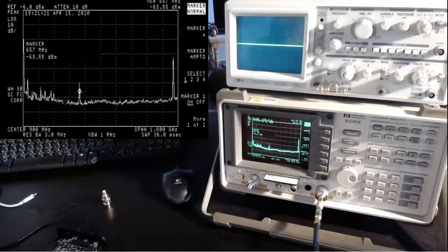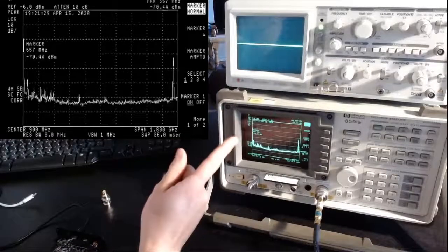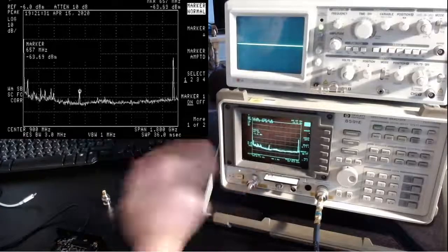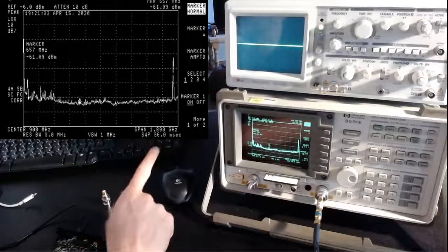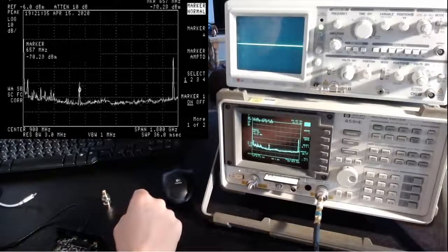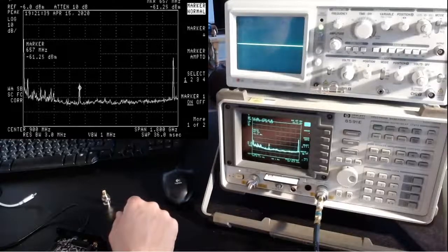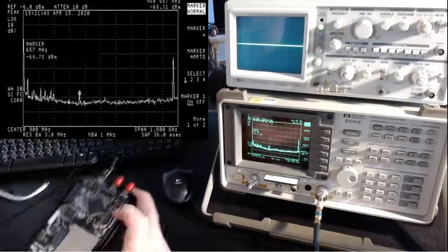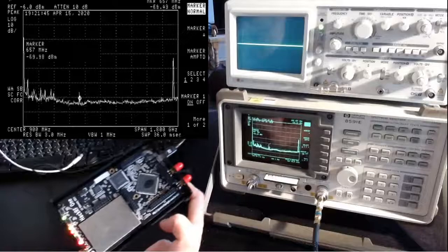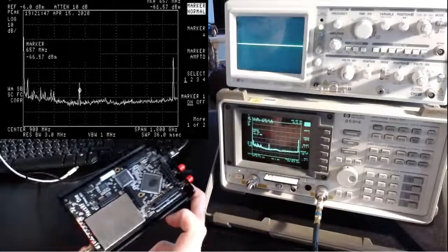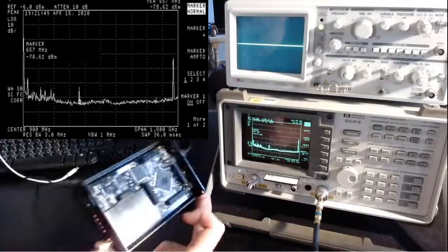But yeah, this was just to give you an idea what the HackRF looks like as a signal generator. It's still a very useful tool. And remember, it can go up to 6 gigahertz. So the spectrum analyzer can only visualize up to 1.8, but the HackRF can actually output at 6 gigahertz. And with proper filtering, it's a powerful tool to combine the functionality of a very basic spectrum analyzer, as we saw in the first episodes, and also for a signal generator.